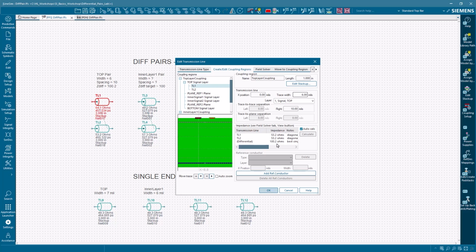Impedance matching is vital in differential pair design. It means carefully designing the traces so that their differential impedance precisely matches the impedance expected by the driver and receiver. Any mismatch will cause reflections, leading to signal distortion and a reduction in the eye opening of an eye diagram, which directly impacts signal quality and timing.